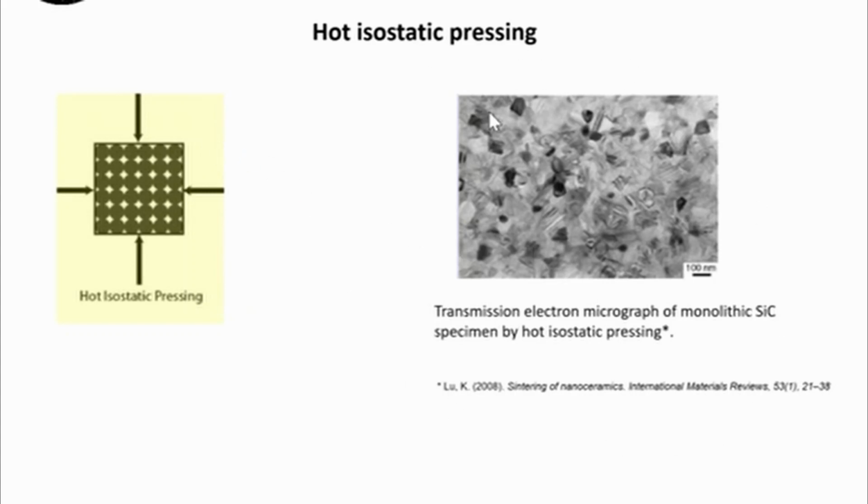For non-oxide ceramics, hot isostatic pressing has been applied to both carbide and nitride ceramics as well as their composites. The relatively more active research activities for these materials are likely facilitated by the knowledge accumulated from micron-sized carbide and nitride ceramics. For example, it's possible using hot isostatic pressing, where the pressure is applied from all sides of the sample. Liu and colleagues showed that nanostructured silicon carbide could be successfully densified by the HIP process.